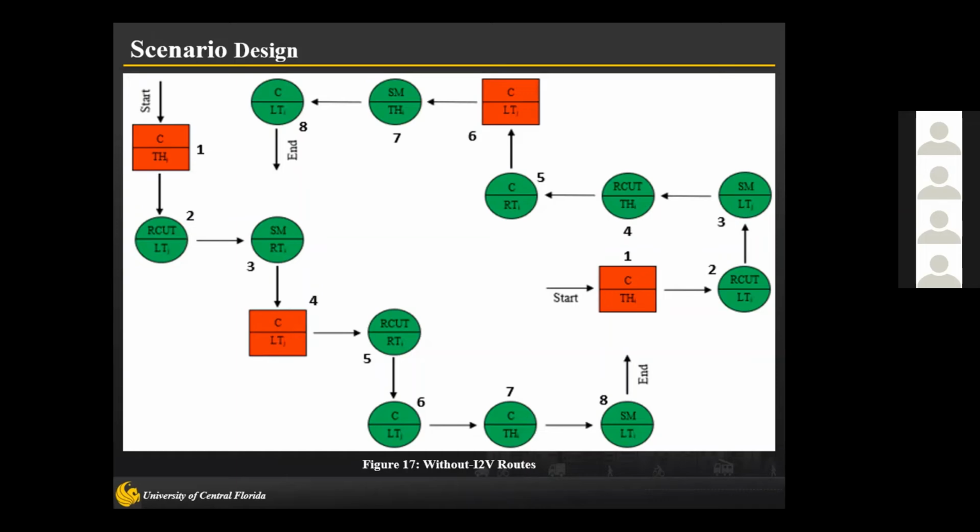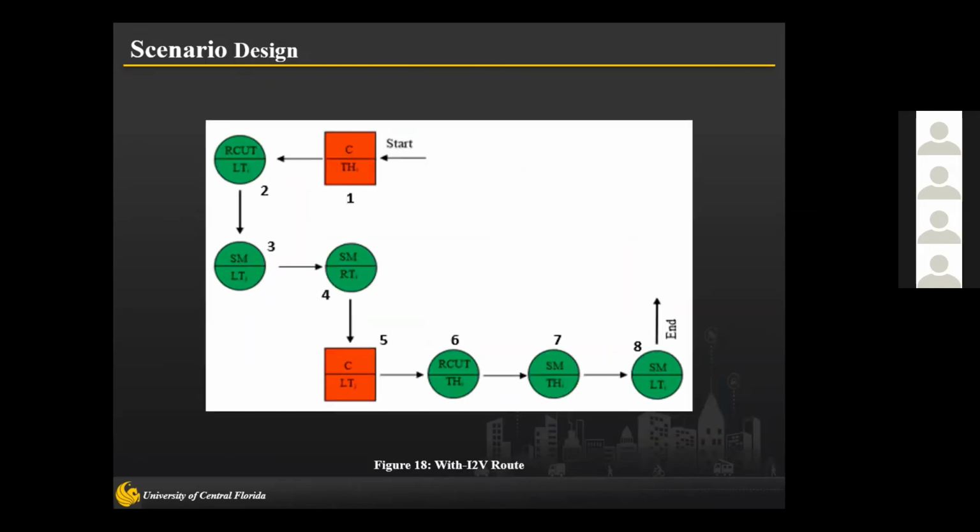To give the driver time to engage in driving before considering the data for analysis, the driver was directed in all routes to do a through movement at a conventional intersection, where the data of this movement was not accounted for in the analysis. A spacing of 0.8 mile between intersections was provided to give the driver enough time to go back to normal driving behavior before reaching the next intersection.